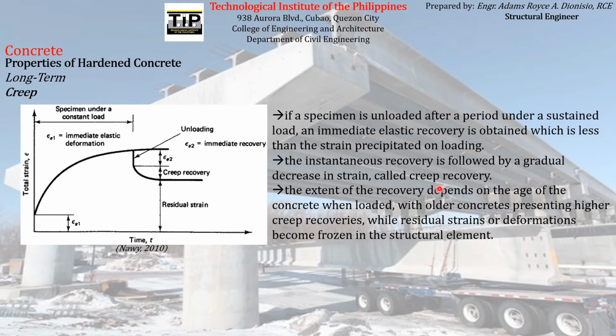The extent of the recovery depends on the age of the concrete when loaded, with older concretes presenting higher creep recoveries, while residual strains or deformations become frozen in the structural element. So you can see that older concretes tend to have higher creep recoveries.